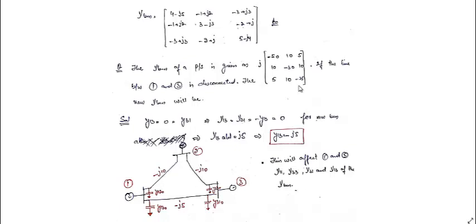This is minus 10j. This is the admittance connected between 1 and 3, sorry, bus 1 and bus 3, that is minus j5. The matrix element is j5, so this is minus j5. Similarly, y21 and y12 will be the same. And then y32 and y23 are again plus 10j in the matrix, so here it will be minus 10j. This will be our power system.